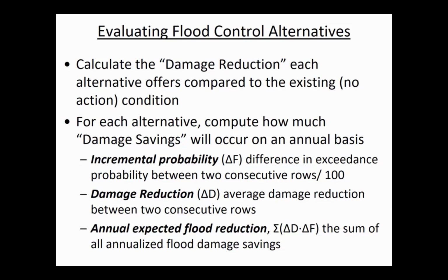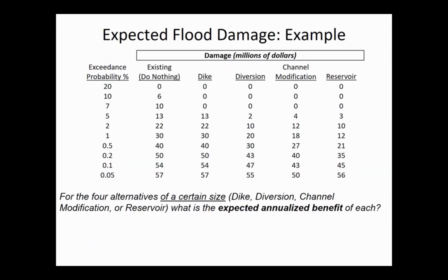And so you combine it all together. You know, there was a 10% chance that this was going to happen and a 20% chance that that was going to happen, and you add up all of the things that were prevented. If you're building to the 25-year storm, you're protecting against the 25-year storm, so you now can avoid the damage of the 2, the 5, the 10, everything below in size, below and including the 25, has been avoided. And so you get to accumulate all of those probabilities and all of the costs.